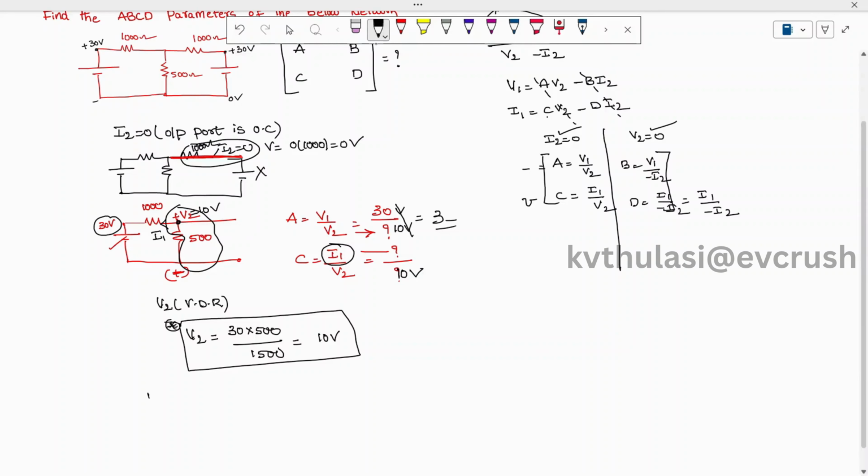The general formula is I1 equal to V by R. The voltage at this point is 10; the current leaves the terminal that is plus, while the leaving terminal of this voltage is minus, so it is high potential minus low potential divided by R. R is 1000. When you perform this, you get the value of I1 as minus 20 milliampere.